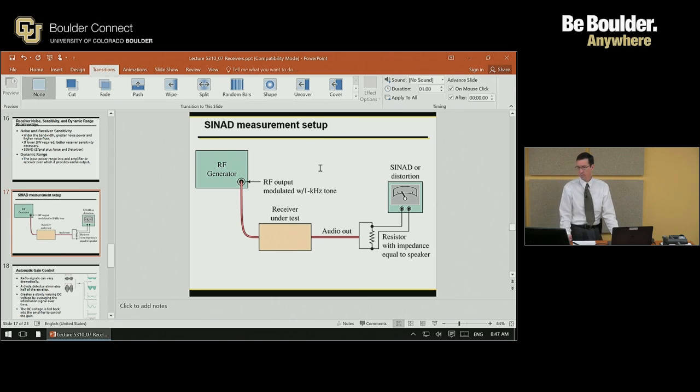And then what happens is if you've got a receiver and you know what the specifications are supposed to be, because the specification will come with a SINAD number with it, you can go and set up your own test and verify if it's meeting the performance level. If it's not, then you know that something has happened. It might be in the IF stage. It could be elsewhere.